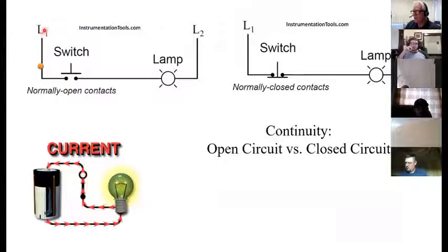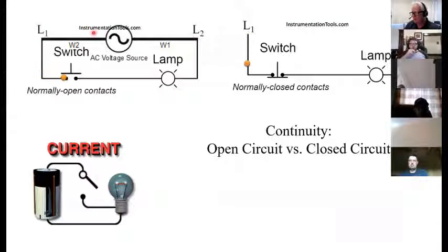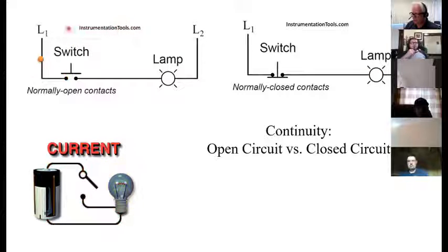This is one side, and there's nothing that's drawn connecting this, but we're assuming that there's an AC power supply that's pushing current through this way and then returning this way, and I've got my loop. So you'll see drawings that'll be indicated like this, L1 and L2. Know that this is like the prongs of a plug on your lamp. This plugs into one slot and this plugs into the other. There's something behind it.